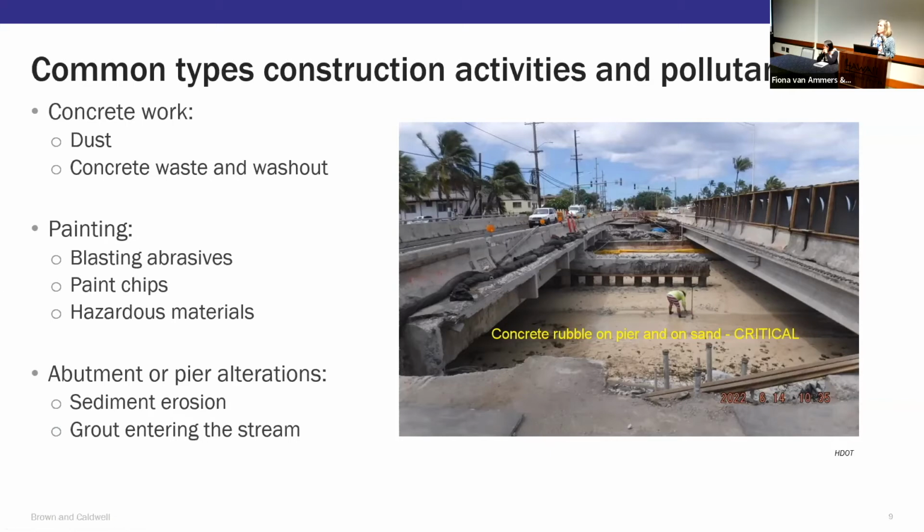So a lot of the activities that you'll do have the potential to create sediment. Sediment can smother habitat in the water. Basically, the sun can't get into the plants. They will not grow. And then the fish don't have plants to eat, et cetera, et cetera. Sediment also carries nutrients like phosphorus and nitrogen. When that gets into the water, we see algae blooms. When algae blooms die, they decompose and they use the oxygen in the water, takes all the oxygen out of a waterway, and you basically are suffocating fish.